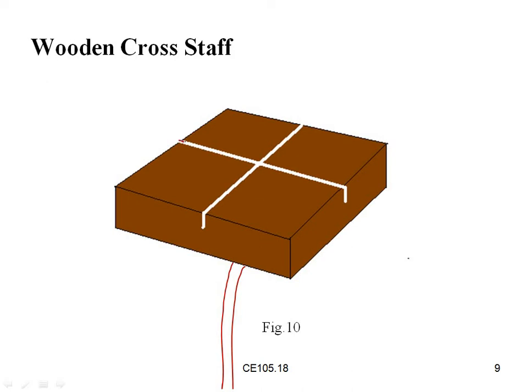In these lines a small gap will be there, and in this gap we will be sighting the object, either from this side to this side, or from the other side. Suppose the object, a ranging rod or anything, is here; we will sight that point so that these points will be in a straight line.